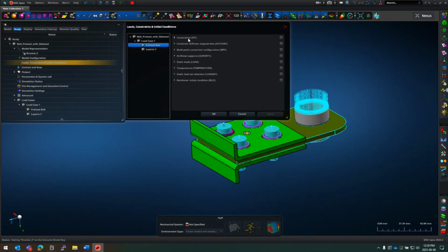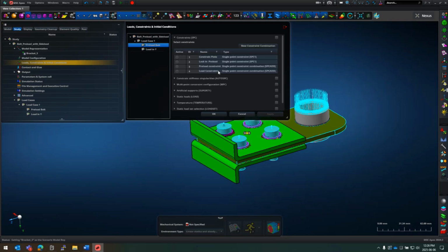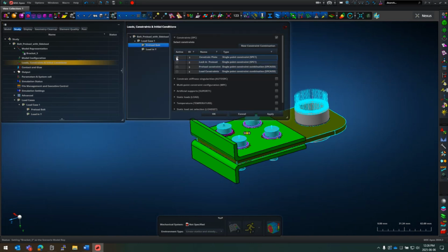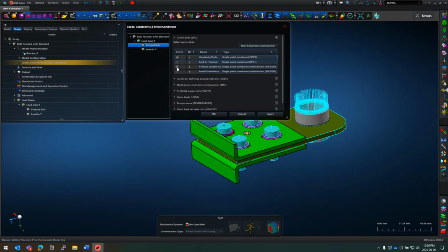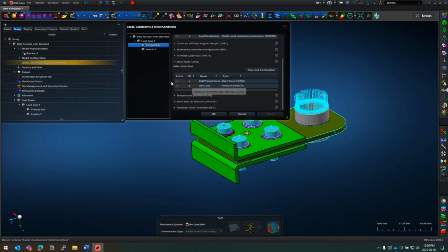So I'll rather specify on this level. So for the preload constraints, I specify, well, I've conveniently called it preload constraints, and I can pick one of the others, but only one of them. Okay, so in this case, I just picked that one, which is why I created that constraint combination, and for the loads, I can specify I want to apply the bulk preload as well.